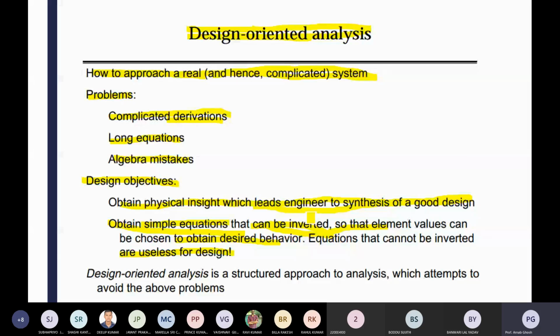So why is that inversion important? If you have one converter having 2 poles and 2 zeros, and you go for inverting the transfer function, there should not be any problem, and it should be the proper one. But some converter transfer functions, like the boost converter and buck boost converter, have one zero in the right hand plane. RHP zero means a right hand side zero.